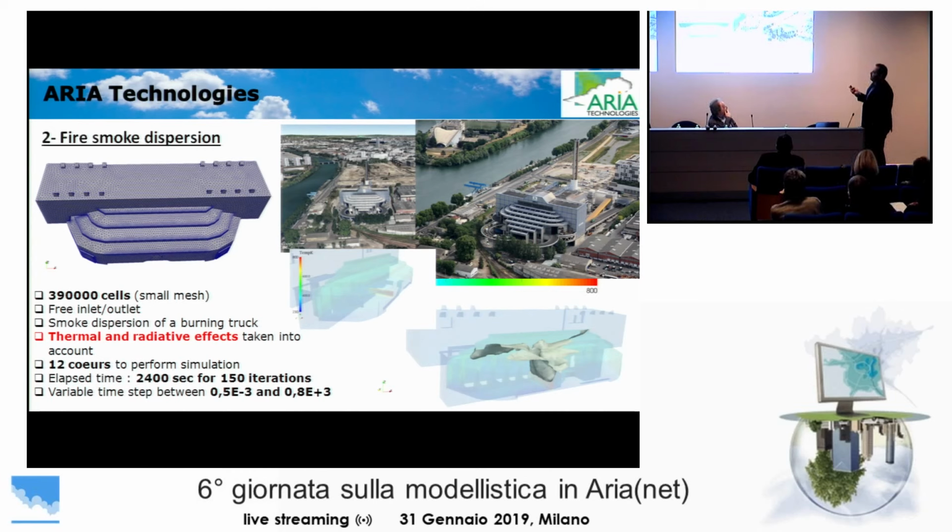We performed the simulation on 12 cores, 2040 seconds for 150 iterations. And we used a variable time step to accelerate the convergence. So the time step varies between these two values, so there is a big gap between the minimum time step and the maximum one.